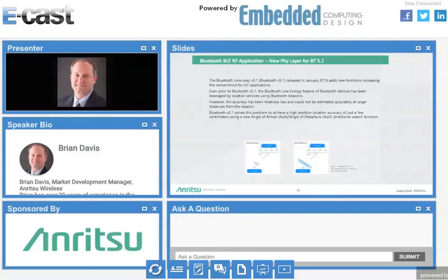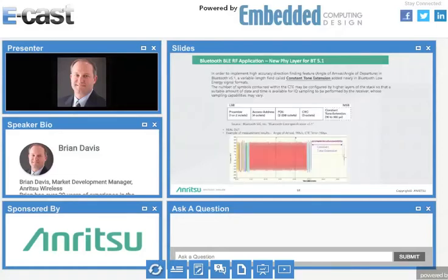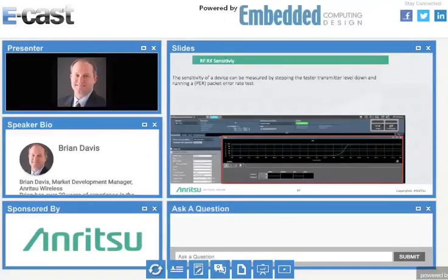In Bluetooth 5.1, the latest is actually 5.2, but that just got approved in January this year. 5.1 offers this angle of arrival, angle of departure capability for location finding devices, so we can measure that now as well. There have been some changes to the PHY layer in 5.1. There's this constant tone extension that's been added after the cyclic redundancy check. So we've got that ability built into the equipment.